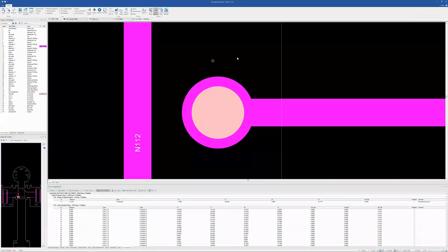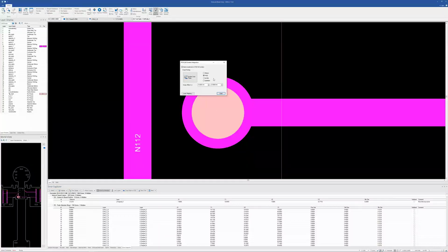Okay. And then the last thing we did with CAMView is we give you the ability to cross-probe. So if you're a user of any of these CAD tools, you can be looking at the error here in CAM350 or CAMView as well as in your CAD tool at the same time. It'll search for the proper layers, the proper location, turn those items on in your CAD tool.